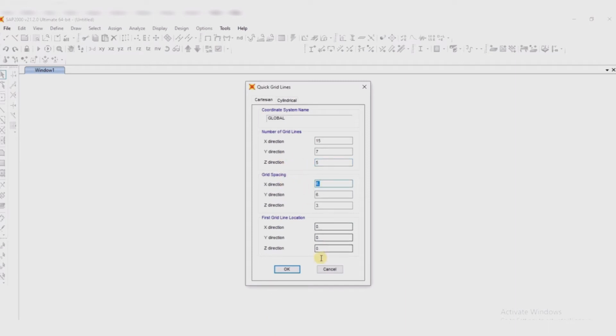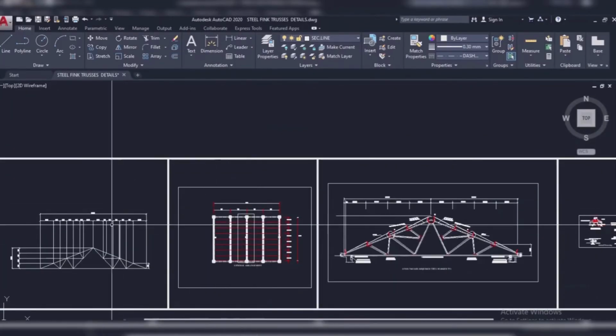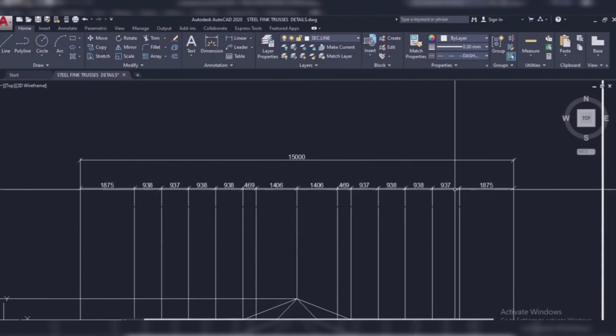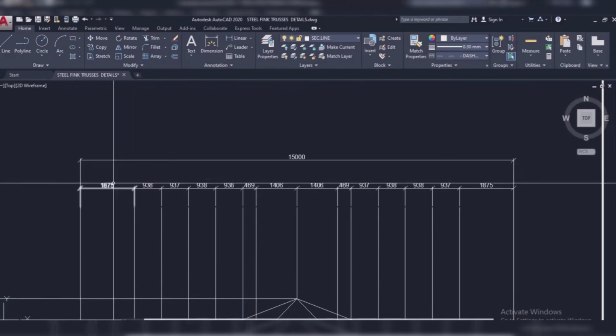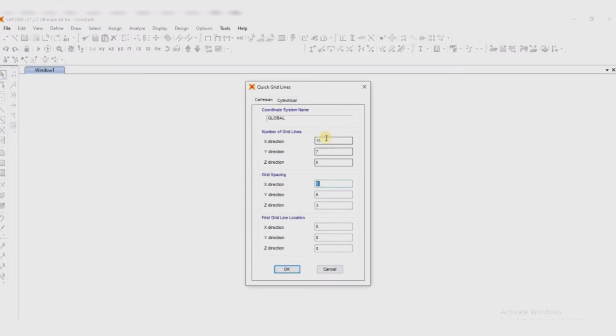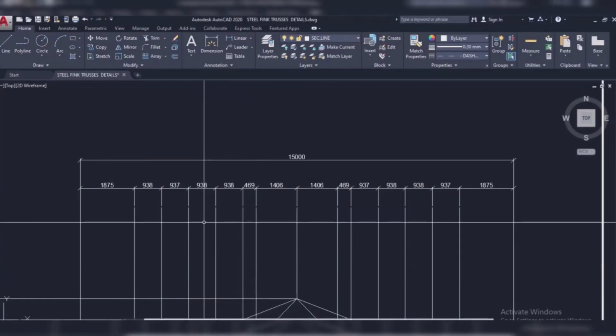So these are the spacing along the x-axis, and if I will need to input all this spacing, that means I will first input the initial spacing, and the initial spacing can be any number value. For example, let me use 3 meters, and the spacing along the y-axis is 6. I told you that is the spacing from one truss to another. The spacing along the z-axis is constant, and that is 0.750. You can see it from here now.